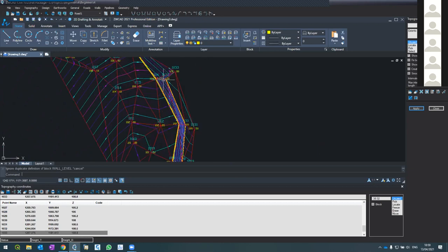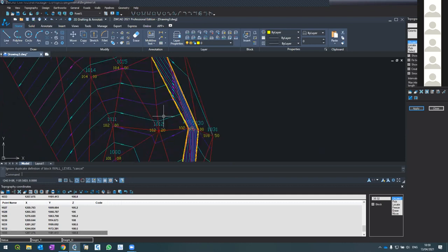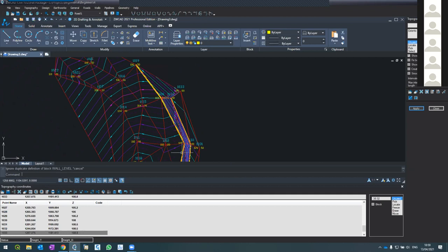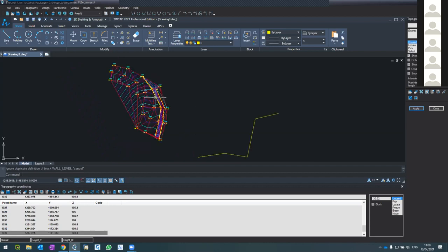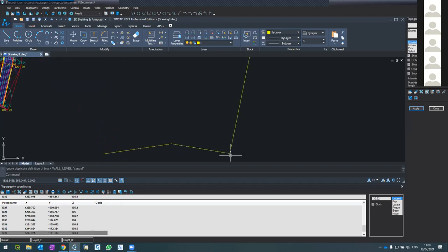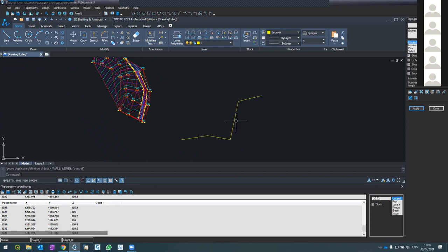In fact, let's summarize the issue of breaklines. A breakline is a mathematical problem, but it says that 2 points are interpolating and we don't want them to interpolate. The solution is to create a breakline, which breaks the interpolation. Points on one side of the breakline do not interpolate with the other side. The interpolation is to the breakline and from the breakline. In practice, in the field, since we don't know when to interpolate or not, we create breaklines when we have gaps or sharp gaps.